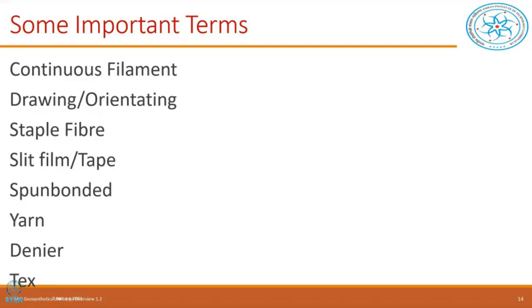But in our case now, it is being pulled in the axial direction. And that means now the molecules of the polymer are oriented in the axial direction now. Earlier, they were crisscross, they were randomly oriented. Now they are coming actually into a shape of longitudinal direction. And by that process now, because we orientated them now, the strength increases by 10 to 100 times. That's why I said when you just take it out of the extruder now, you can just feel it and it will get broken very easily. But once you are pulling along at a given temperature, naturally, they are going to be becoming stronger and stronger now.